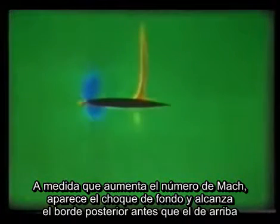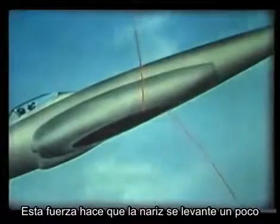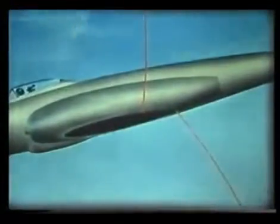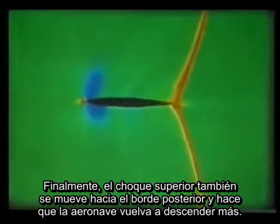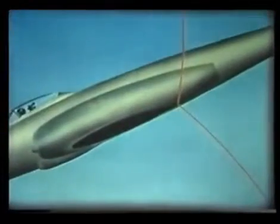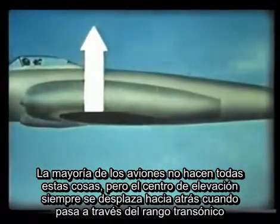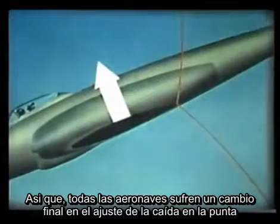As the Mach number increases, the bottom shock appears and reaches the trailing edge before the top one. This forces the nose up a little. Finally, the top shock also moves to the trailing edge, making the aircraft go more nose down again. Most aircraft don't do all of these things, but the center of lift always shifts towards the rear when passing through the transonic range. So all aircraft suffer a final nose-down trim change.